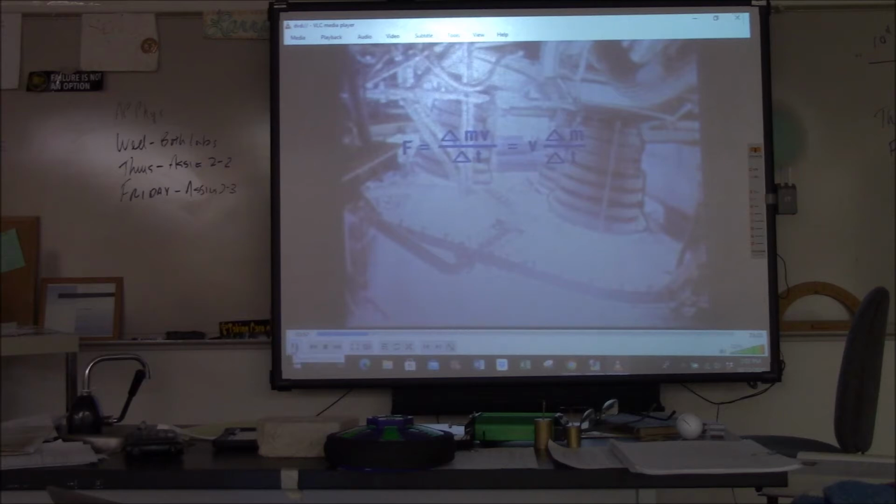Consider a single space shuttle main engine, with the propellant gases being ejected at a velocity of 3,600 meters per second, and at a rate of 470 kilograms per second. The resulting thrust generated by the engine is equal to 1.7 million newtons. So 470 kilograms per second is like a small car consumed every second. As per Newton's second law, the greater the fuel rate at which the hot burning gases are exhausted, and the greater their velocity, the greater the resulting thrust will also be.